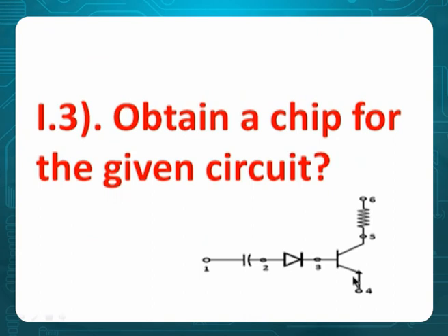If you see from my block diagram and flow diagram, that is after the physical level, just before fabrication. So from the design idea, it goes to behavioral, from behavioral to data flow, from data flow to structural level, from structural level to device level, and then this circuit is achieved. For this circuit that we achieved, we are going to make a fabrication and make a chip for it.